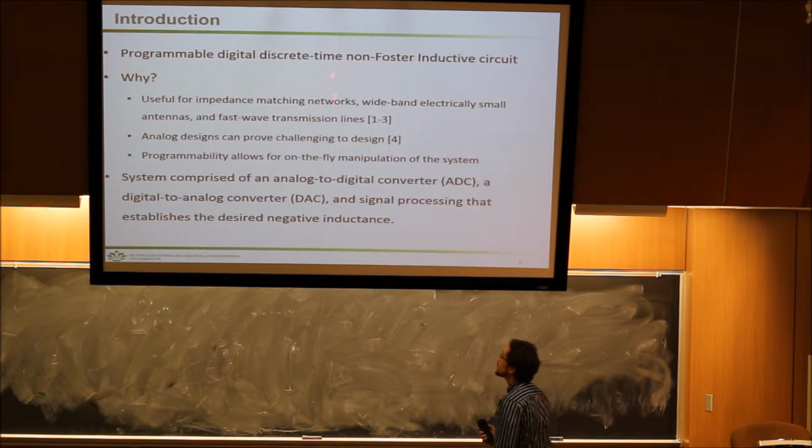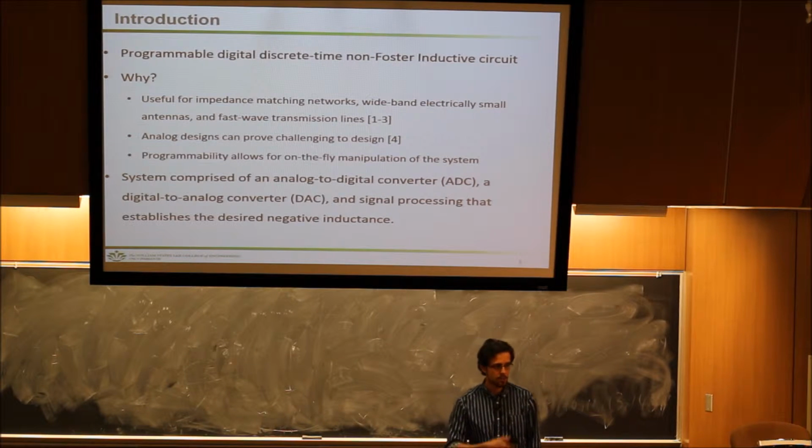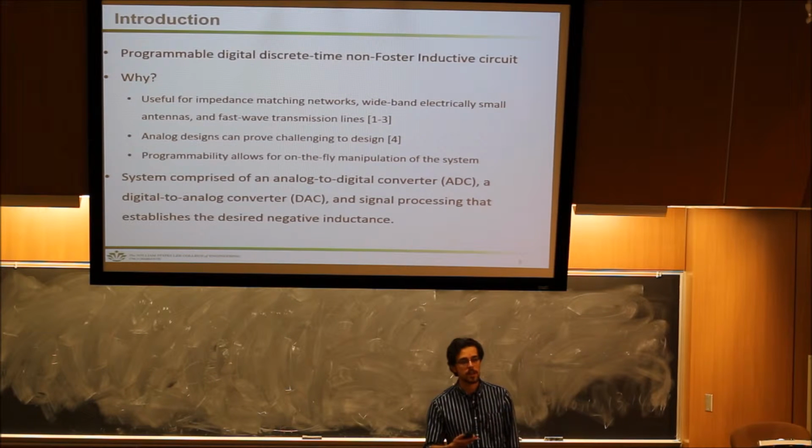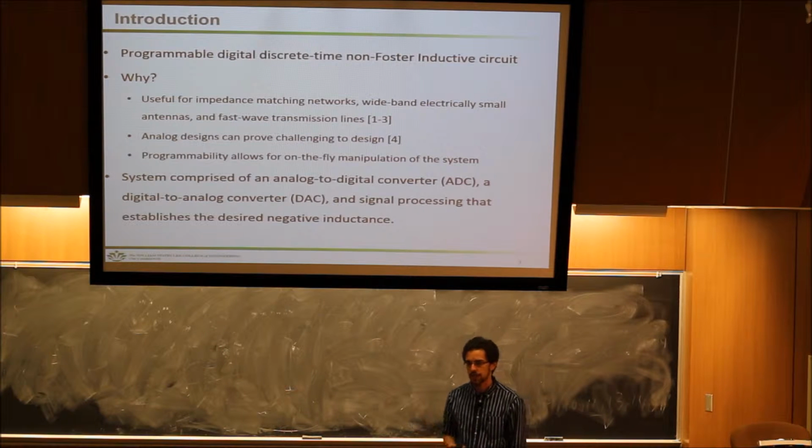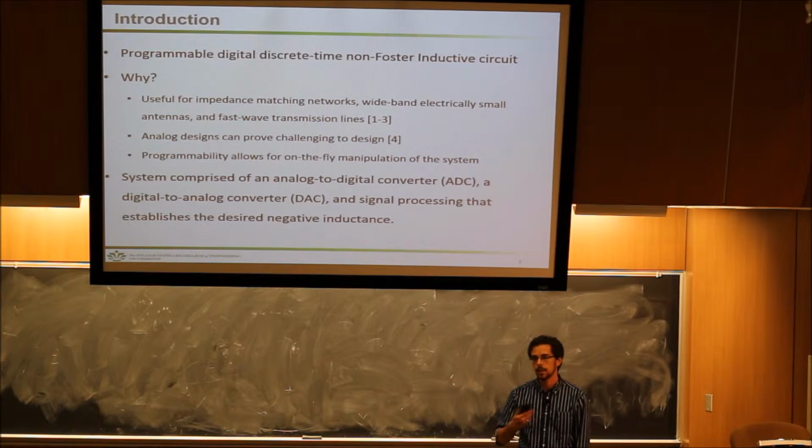Well, this has a lot of applications in impedance matching. Since we effectively have a digitally reprogrammable inductor, instead of people building impedance matching circuits in an analog sense, putting them on a circuit board, soldering them down, and putting them in line with the system, now they could put our system in the middle of that. If the system somehow changes, with components changing over time, with heat, or they want to change their system up a little bit and don't want to buy a whole other circuit board, they can just reprogram it. And since it's an Internet of Things schematic, they don't even have to jack into it and plug into it anymore. It can all be done over the network.